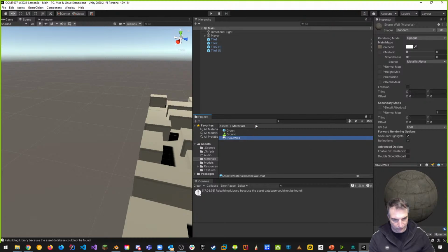And this is a way of using a very low polygon object and adding detail to it without modifying the object and making it more complex. For example, if I had to model an object with all these bricks, it could become a very high polygon model, with many polygons. And a high polygon count is bad from a performance perspective because I have to make sure that each vertex and face and all that stuff. Can you imagine making a model with all this detail? It's too much, right? So we use a texture instead.